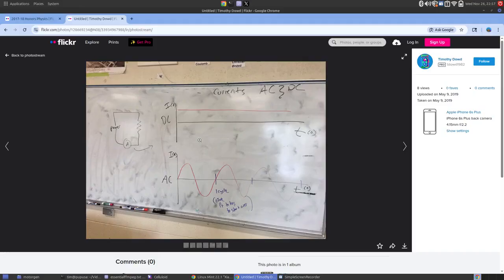Alright, so how is this strange pulsing we're seeing on the galvanometer representing DC? For a battery-powered DC circuit, we expect a current versus time graph to look like this. Pretty much constant, maybe a slight decrease as the battery drains. And what that represents on the circuit is current leaving the power supply, going through the circuit and coming back, always in one direction.